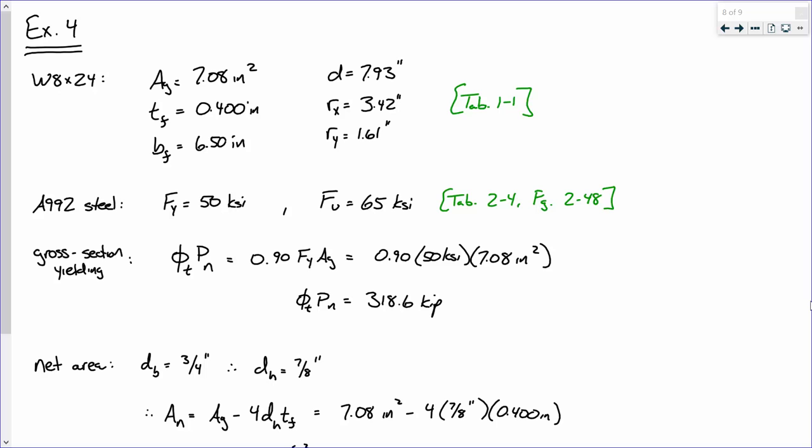I'll say this about rx and ry. We will become experts at assessing things like slenderness later when we look at columns, when we look at members subjected to compression. Members in compression behave significantly different than members in tension because members in compression like to do this little thing called buckling. So that becomes a whole another can of worms later. For now, we're just looking at basic slenderness calcs, so we'll just go off of our ry.